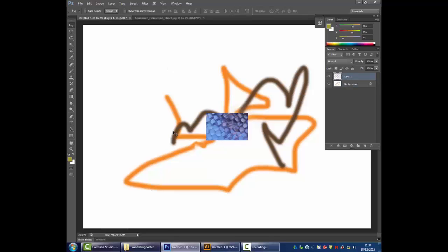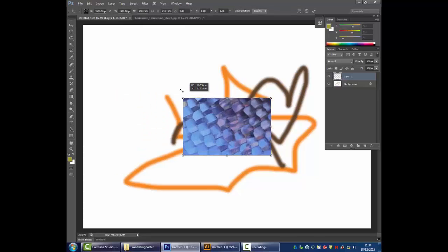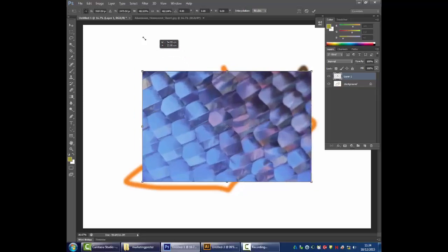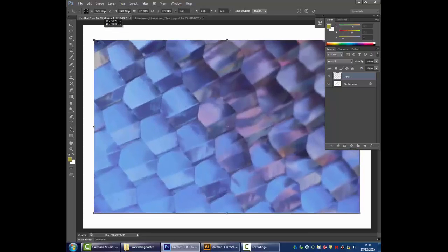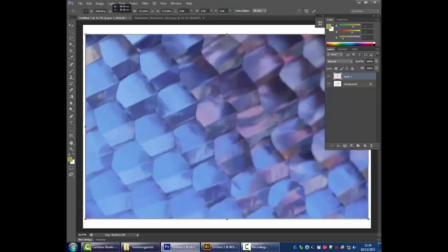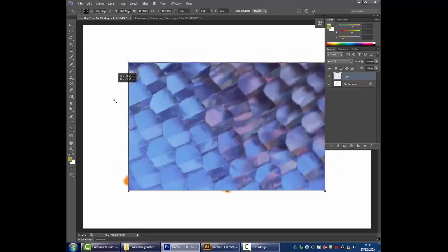As you can see, on the screen it was quite a big image, but when it comes into this big A2 image here, it's pretty small. Now if I go Edit, Transform, Scale, I can make it bigger. Here, I'm scaling from the middle, and it's locked XY aspect ratio, so I'm not stretching or squishing it. I'm doing that by holding down Shift and Alt together.